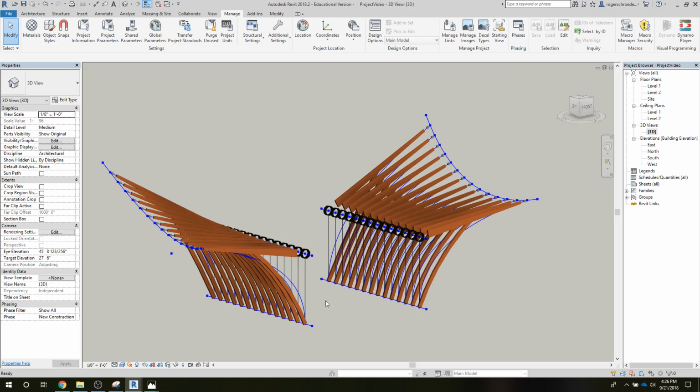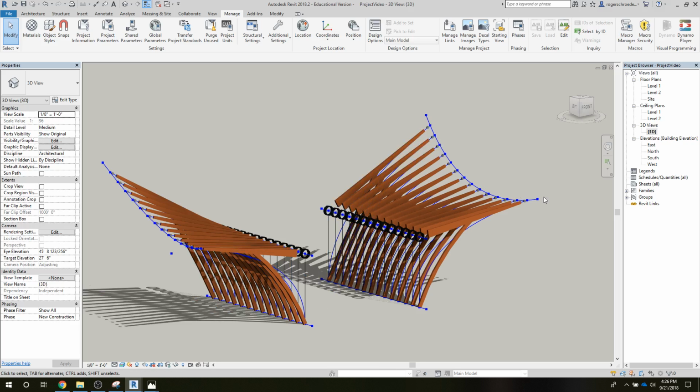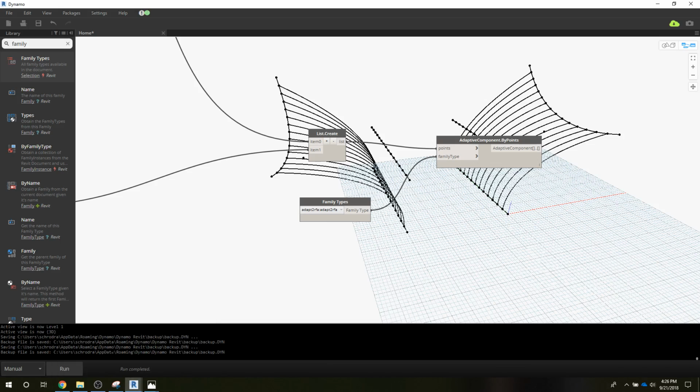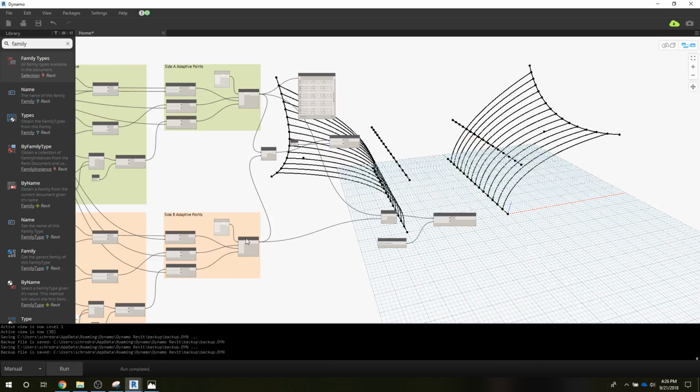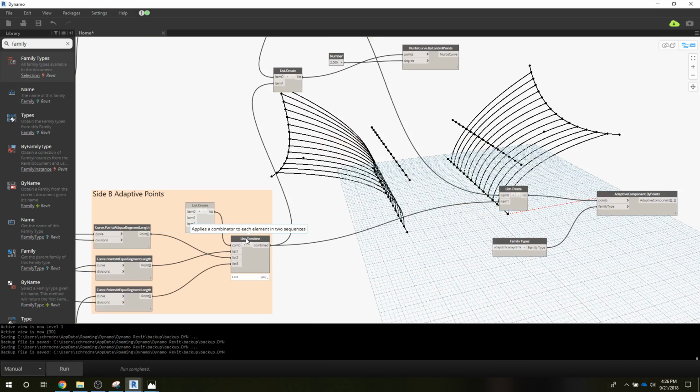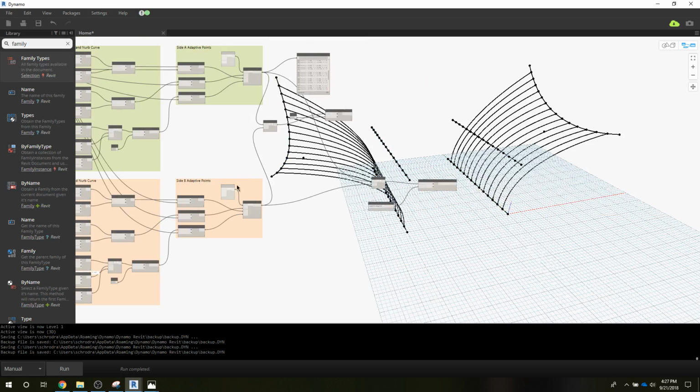So we have all of the lines that are showing right now. We can get rid of the blue lines that are distracting by going into Dynamo, as you might know already, and taking the previews off of all of the elements that you see. If you right-click on any of these, we can turn the previews off. That's a little bit tedious, you have to go through all of those, but I wanted to keep this relatively concise as far as the discussion goes.